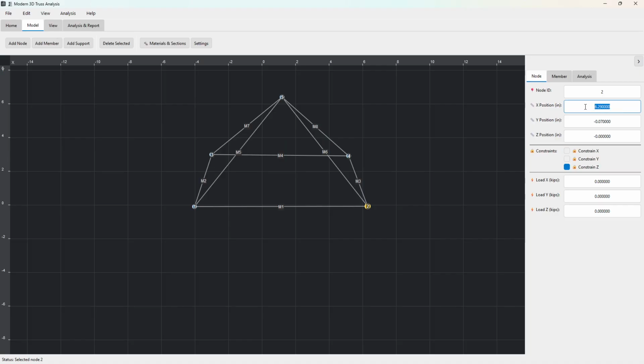to tell you about the unit aware inputs. So I want to place node 1, which starts and places at the origin, 0 0. You can drag it. If you have snap, it will. Let me turn snap on by pressing S and then drag it to the origin, and you can see it's put to the origin. I'm gonna turn the snap off.